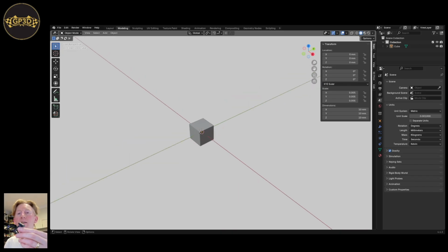So I'm going to use a Boolean operator. I'm going to use a mirror. Pretty much everything that you do often has a left and a right, or it's symmetrical, or at least symmetrical to some extent. It might not be 100% symmetrical. This object is, by the look of it, 100% symmetrical. And the way we do that is using a mirror. It's another modifier called mirror. So we've got the Boolean modifier and we've got the mirror modifier. I think that's probably all I'll need to show you to make this object.